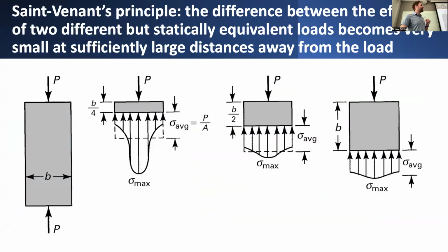All right. Now, there's an interesting thing I want to point out, and we talked about it last lecture: this notion of Saint-Venant's principle. It's the idea that if I have elasticity solutions that include very localized forces, like a point load applied to the boundary of some domain, this kind of concentrated load will result in nearly infinite stresses in the local vicinity of the point of application. But if I move further and further away from this point, the stresses start to spread out.